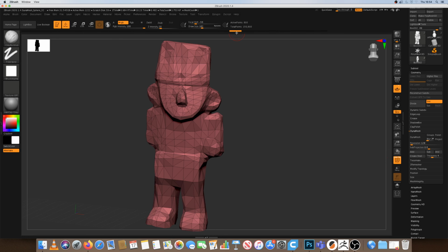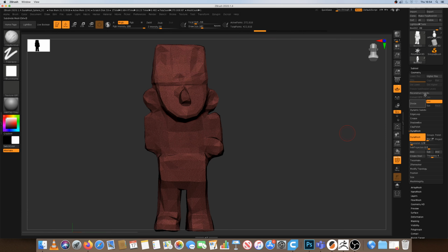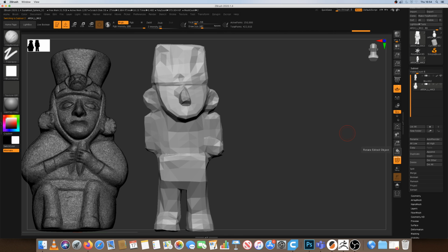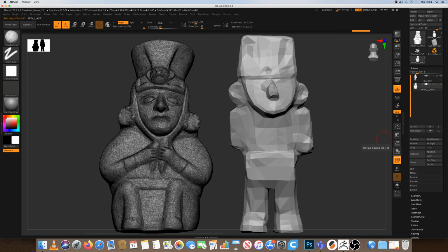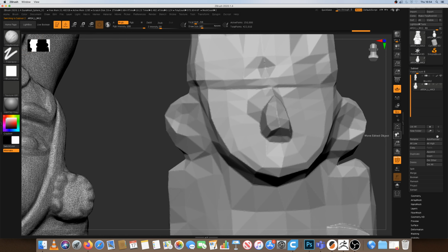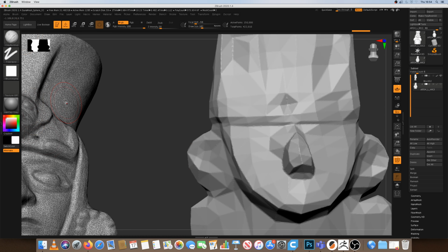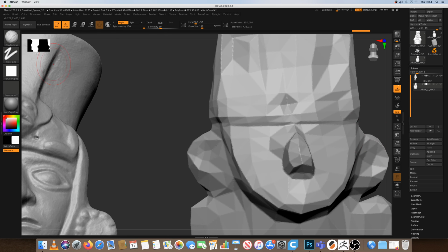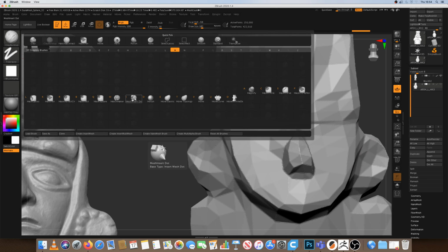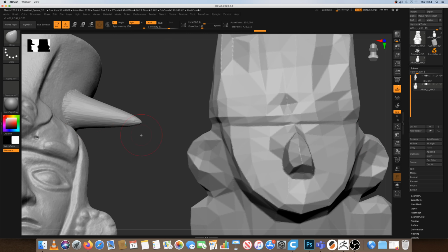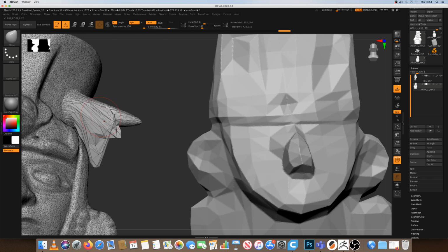So Dynamesh this one, and now we're going to go to the other one. I'm going to perform the exact same thing. This surface almost looks like it's Dynameshed, but it isn't in fact. It still has a surface made up of small triangles. So again, if we tried to edit the surface, we would see that it would very quickly begin to fragment like this, which we don't want. And that's caused by the triangles stretching in a kind of weird way.